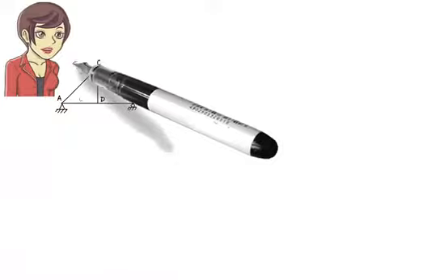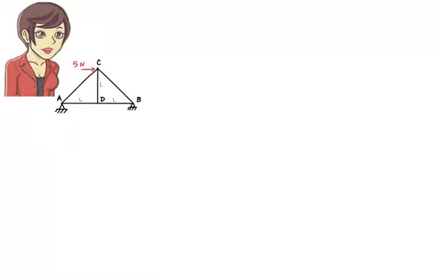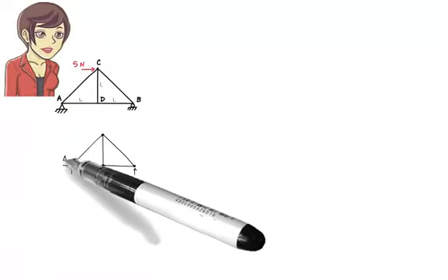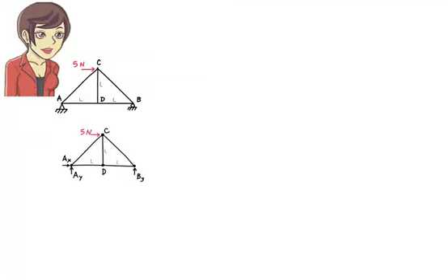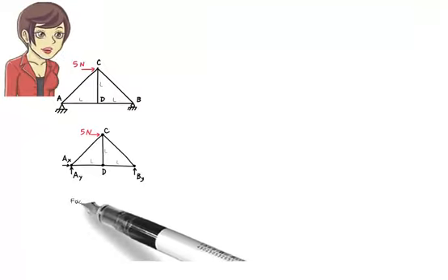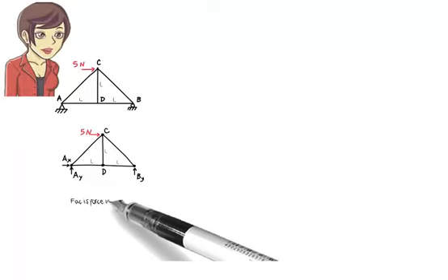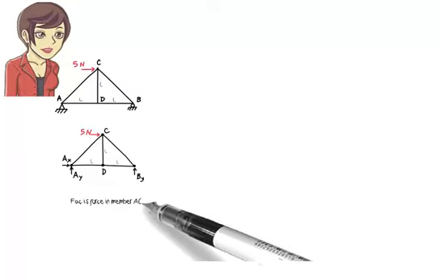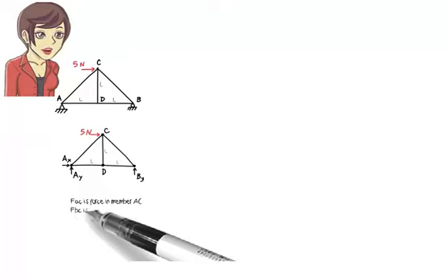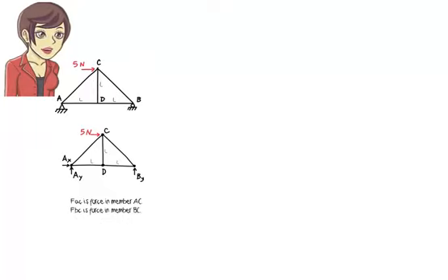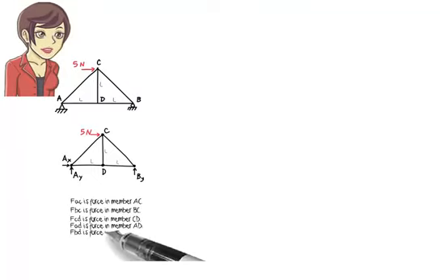Here is our simple truss. Let's draw the free body diagram of the entire structure. Keep in mind that each truss member carries an axial force only. Let's refer to the axial force in member AC as FAC. Similarly, let's call the force in member BC FBC. We denote the force in each of the remaining members in a similar manner.